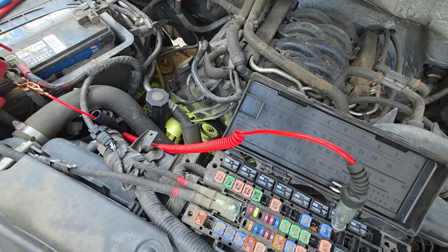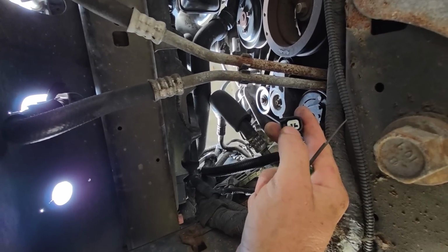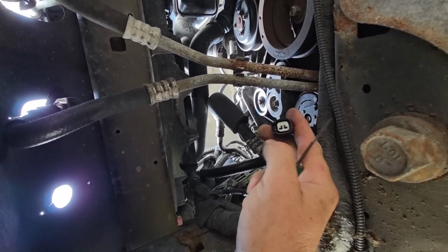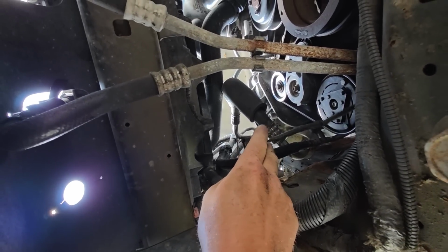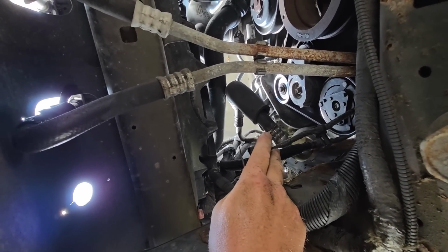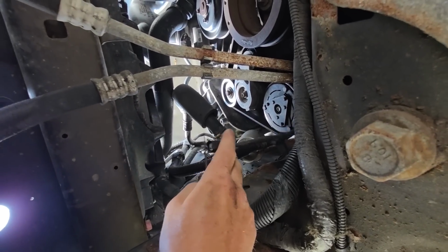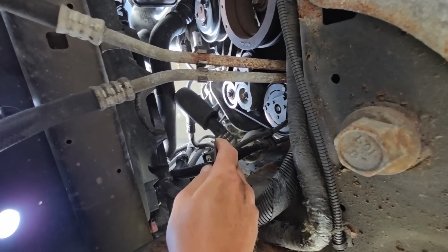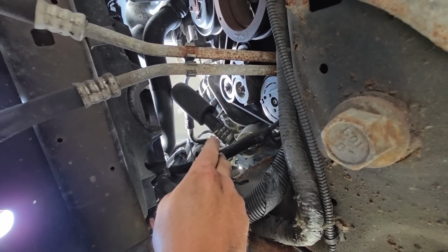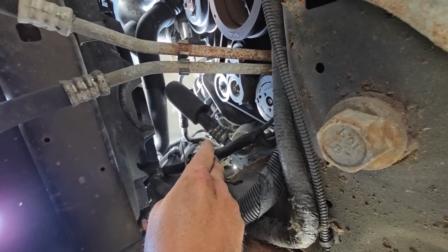I just want to make sure that the wiring is good here. I can't show you guys what I'm doing. What I am attempting to do, because I believe our problem is just loose contacts in this connector, and primarily because the hold down that's about 3 inches to the right of my fingers was not in place, and this harness has been bouncing around. So my problem is either in this terminal, they're loose, or further back, that wire's rubbing on ground or is majorly corroded. It could be that too.